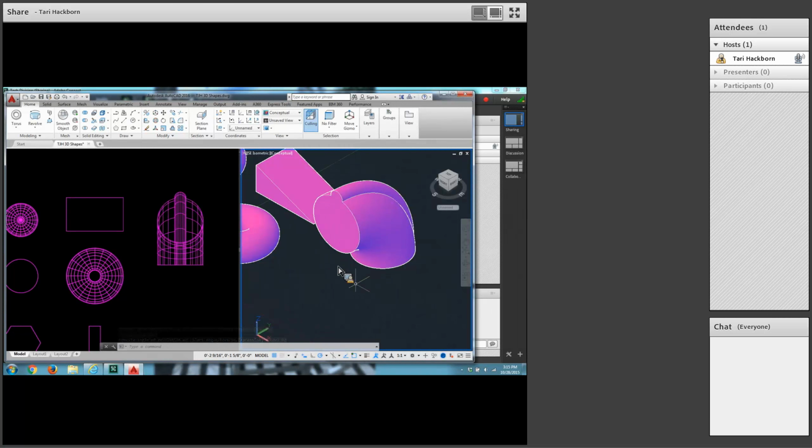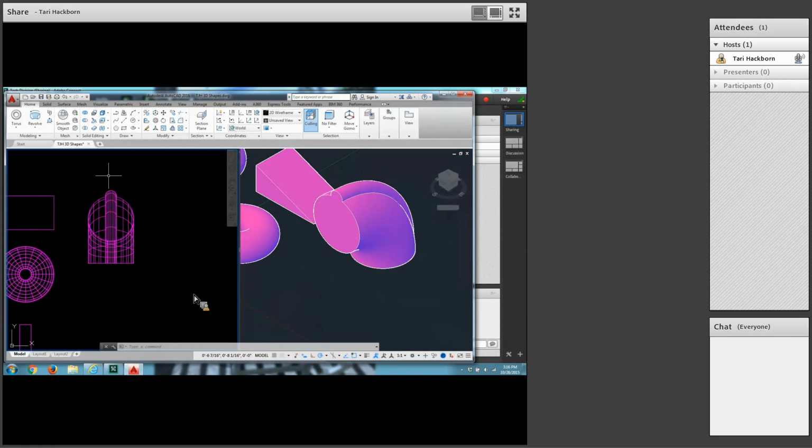Next you're going to revolve a rectangle. I don't know why. I mean, they already had you do revolve. Move over to the top view again. Rectangle right here has a starting point, 7 3/8, comma 7 3/8. Okay, that's the starting point. And then at 7/8, comma 7/8. That's a rectangle. What I don't like about this exercise is all these little fractions they make us type in all the time. Okay, top of the next page.